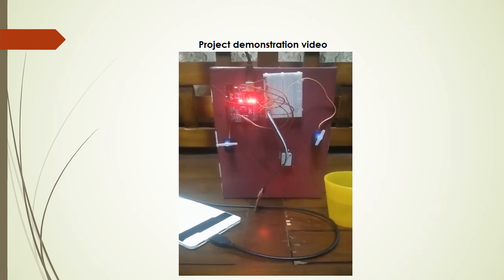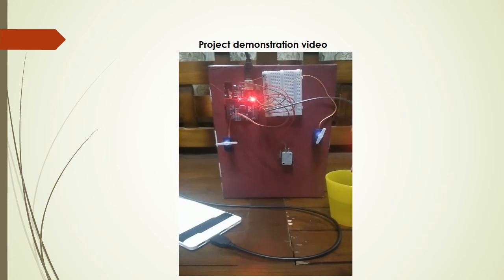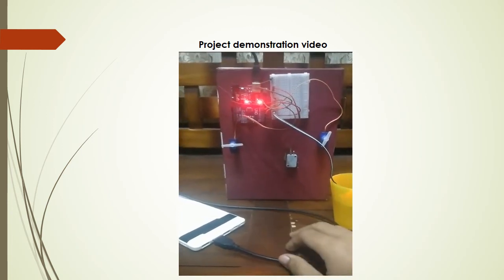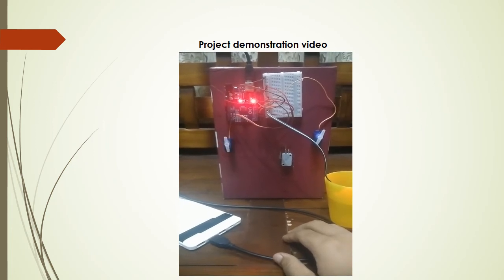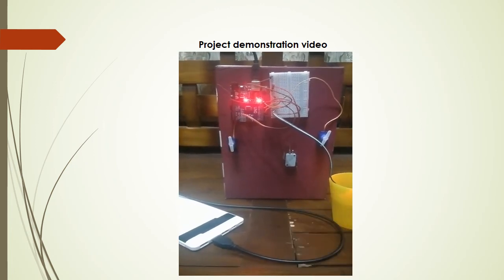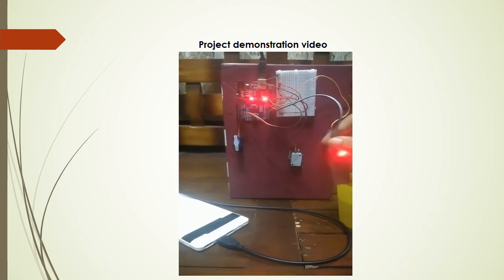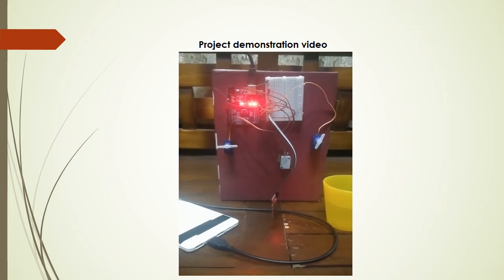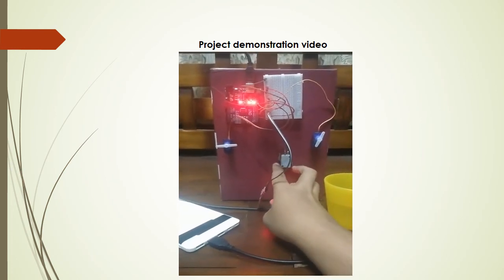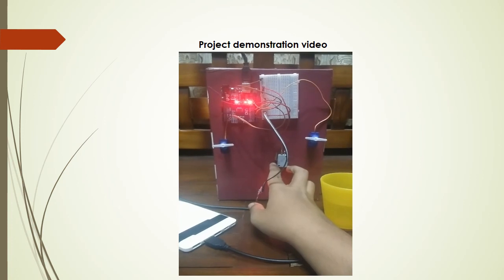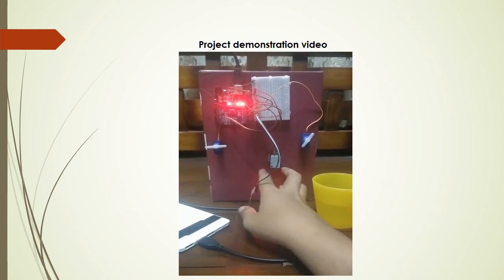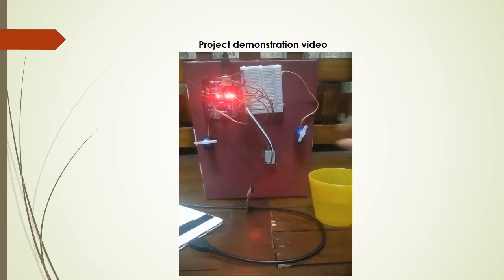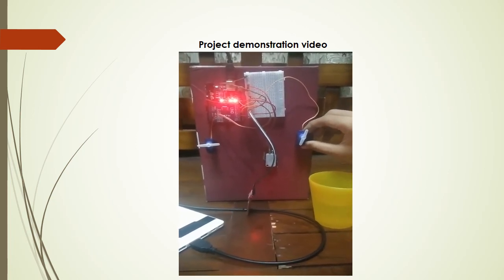Okay, first thing first, when the water sensor detects any water on it, the first servo will move anti-clockwise and clockwise repeatedly, and then it will stop when it detects no water on it. Okay, next, when the limit switch is touched, the second servo will move. The second servo acts as a lifter on the windshield to prevent the windshield from having any scratches.